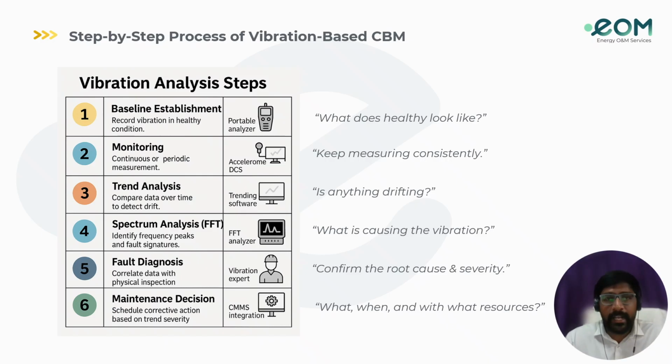And the third one is trend analysis, where we detect changes before the alarm limits are crossed. Plot overall RMS velocity, acceleration, temperature, and selected spectral bands against time. So trend analysis is helpful over time. We need to watch for a slow rise in RMS value, and also sudden level shifts after repairs or startups. The trend analysis shows this with stable warning and alarm comparisons. The next one is spectrum analysis, meaning what's causing the vibration.